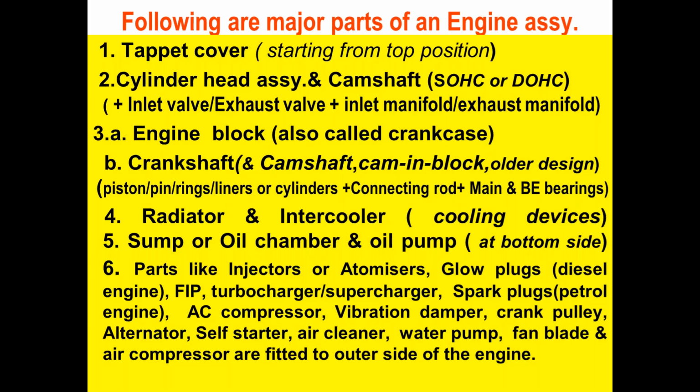Following are the major parts of an engine. Starting from the top position, I have shown you the tappet cover, cylinder head, and camshaft. Now you see SOHC or DOHC. This means single overhead camshaft or double overhead camshaft. Here, the camshaft is fitted over the cylinder head.